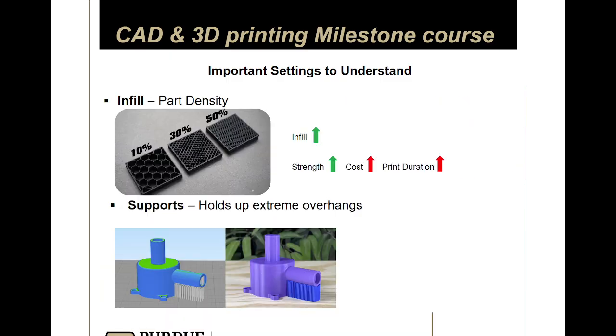Infill is what I was talking about earlier. Again, 3D printed parts are usually hollow on the inside because most of the strength comes from the outside. Hence why I typically increase perimeters before infill. But if you want, you can balance the two. Usually 3D printed parts range from about 10 to maybe 30% infill. I'd say most people stick to maybe 10 to 15. But for parts that are subject to more stress, I typically do like 25% with 4 perimeters.